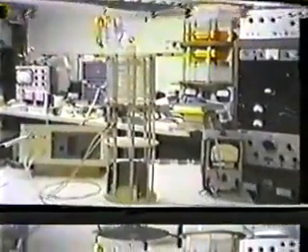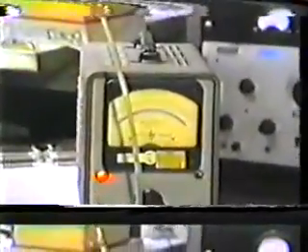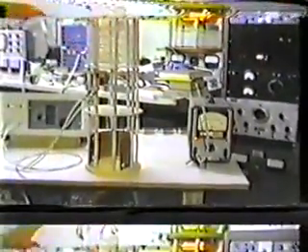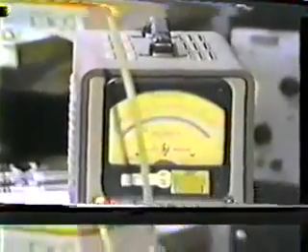Now what we're going to do next is build up a system of analog computers where we can study these waves a little better. With the coaxial cable, obviously we'd have to cut the cable open and stick probes inside to make measurements. In this case, focusing in on the voltmeter, when we use the longitudinal resonance structure, the thing is very sensitive, as you can see on the voltmeter, to any type of changes around it. So if you try to get in there to measure it, you can see by me bringing my hand near the coil that a definite shift out of resonance occurs in the meter. And as an example, I'll keep my hand very close to the coil and find the new resonance peak, and it's gone down about 30 kilocycles just by bringing my hand within 3 inches of the coil. And of course, I bring it away, I have to rehunt for the new resonant frequency.